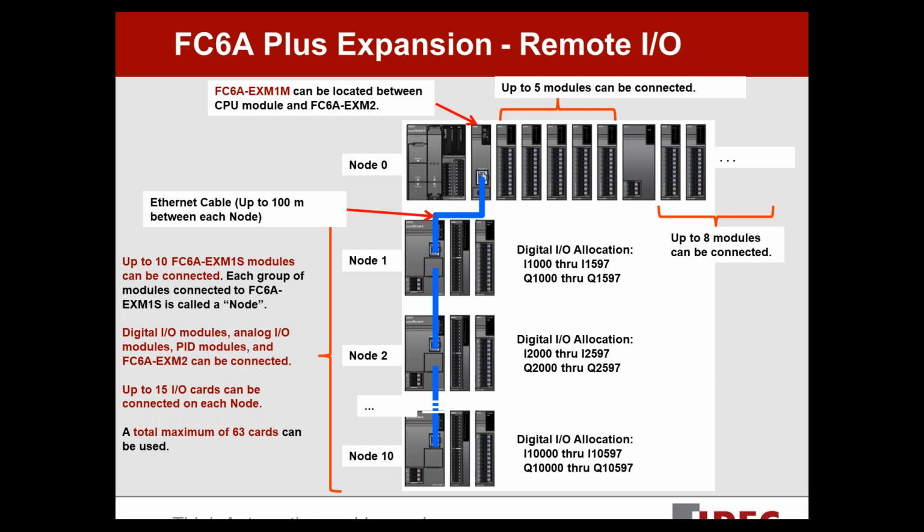All right, now the FC6A Plus supports remote I/O. I'll start up here at the top, and we'll work from the top down and go through this. So at the very top, I've got node 0, my main PLC. I've also got an FC6A-EXM1M, and that is a master remote I/O module. Okay, it's got an Ethernet port on it. You can see that there on the card, and it's got a blue line coming out of it, going to another thing, and we'll talk about that in a minute.